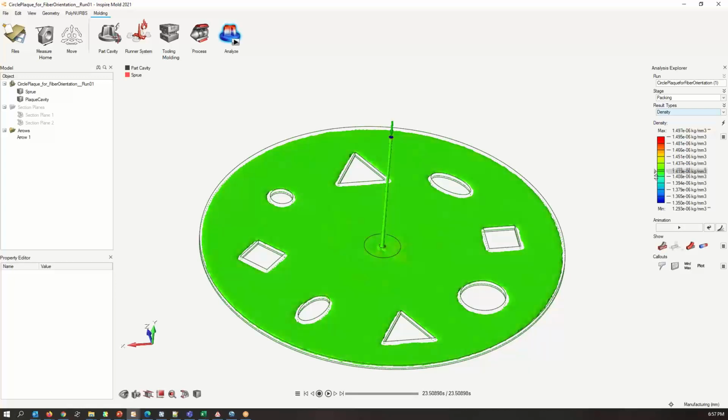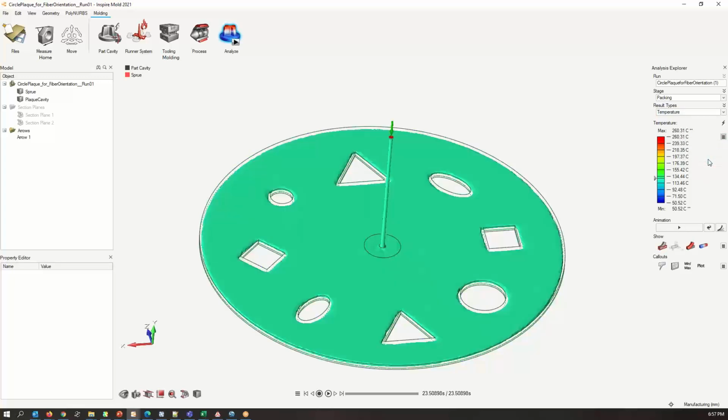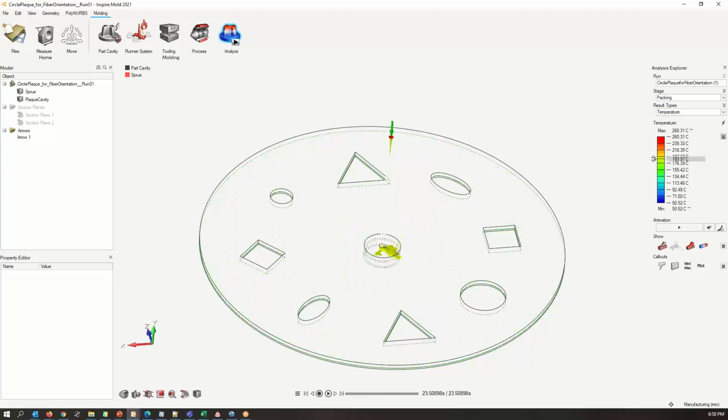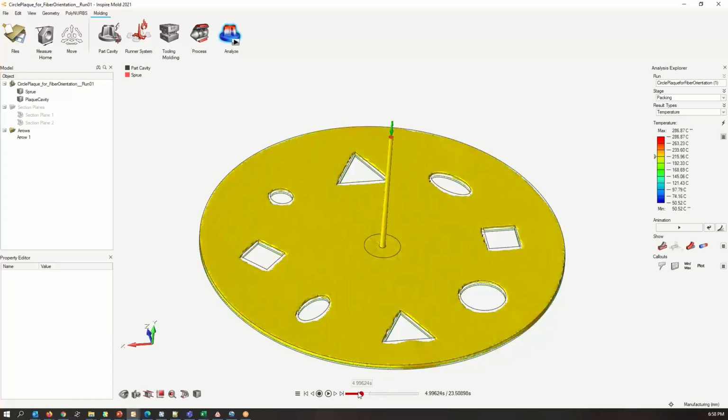And so as I'm pulling back, I can say, okay, there's that. I can do the same thing with temperature too. I come into temperature and I say, okay, now I want to see everything that is above some certain value. So as I'm scrolling down here, I might have to come over here and tell it to invert. So I say flip mask, and now I see everything that is above whatever my threshold temperature is. So I want to see at a given time what is above. I'm going to push this thing up here to like 197, and then I'm going to pull my packing analysis backward in time. If only we could make time go backwards, right?